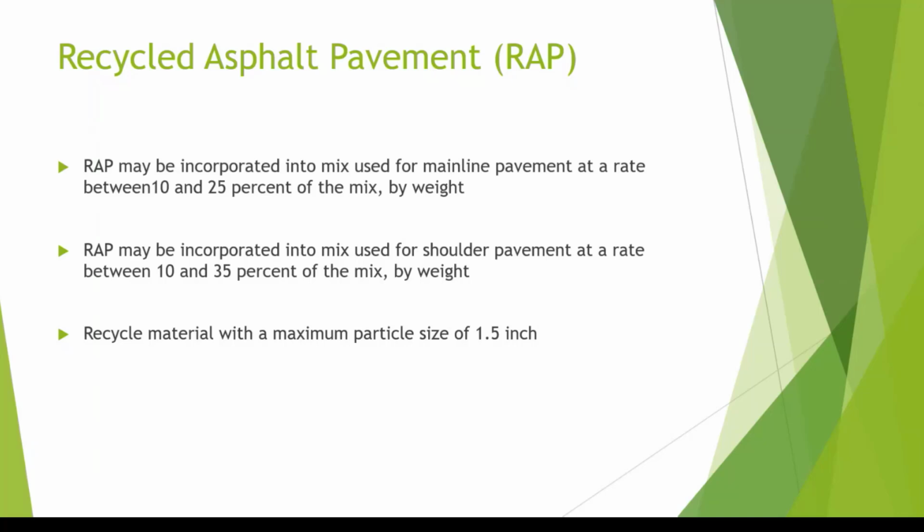That's an important element both for mixing or running it through the drum, but also for heat transfer. The RAP is what I like to call a black aggregate. It's not just aggregate, it's also residual asphalt. So heating any mix is important. Heating a RAP mix and getting uniform temperature is the only way you're going to get uniform temperature out at the road.